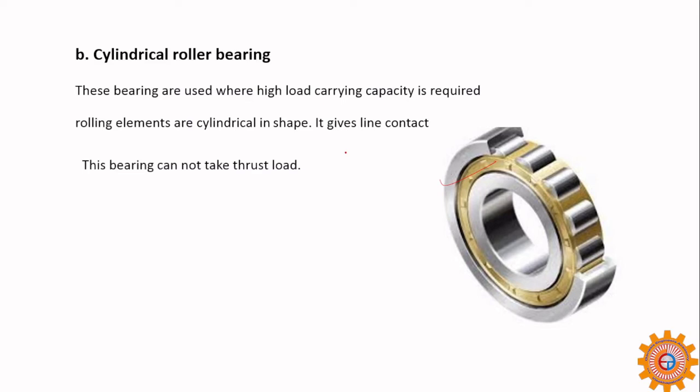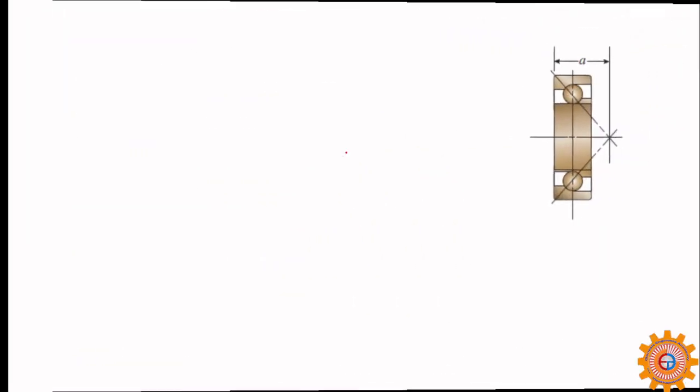This bearing cannot take thrust. Okay, so this cannot be used in a footstep bearing or where there is axial thrust.